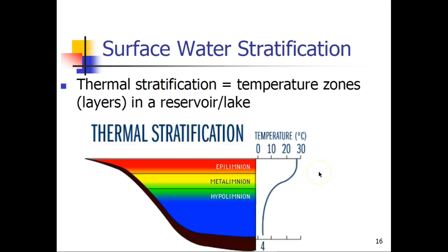Now, one of the things that happens in water and reservoirs is these can actually flip. And all of a sudden, all that cold water literally flips over to the top. And again, this is the kind of stuff that can cause havoc when you're a water treatment plant operator, because thermal stratification and flipping of the reservoirs can happen once or twice a year, depending on the climates.